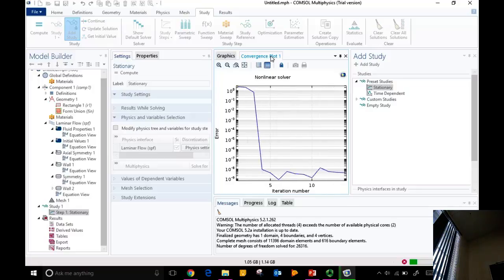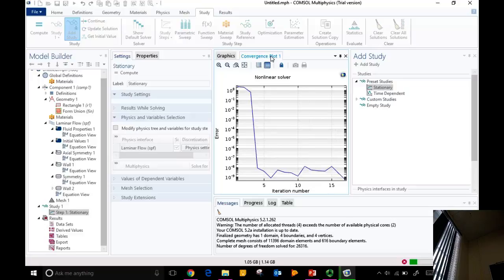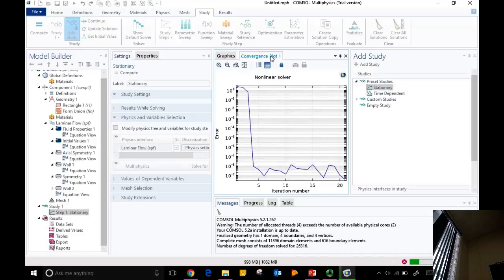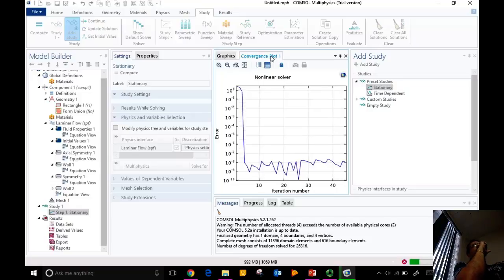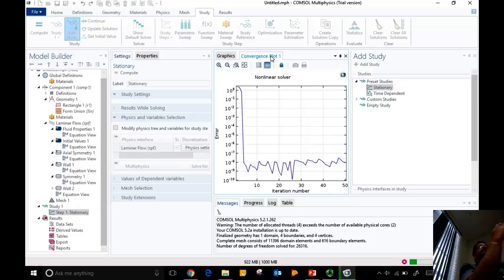Right? Yeah, question. So we add a symmetry boundary condition for having an infinite cylinder, right? Right. What is the difference? Because the equation for the symmetry boundary condition was no force at the boundaries, right? No tangential force and no normal force. We have a free boundary condition as one of our options in boundary conditions, so what is the difference between that one and this one? In some cases, they are the same. We can go and look at what equation it imposes on a free boundary. A free boundary is one where you have a free surface, a liquid in a tank.